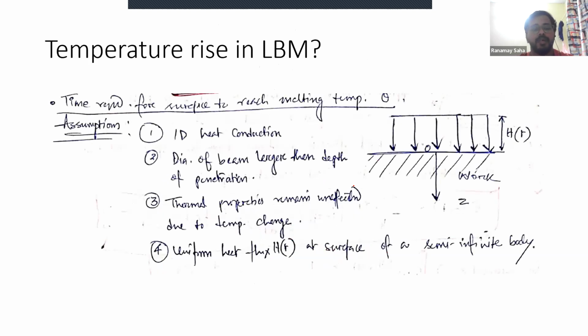Now, we can similarly look at the temperature rise in the case of LBM. However, this needs some assumptions, such as the heat conduction that we also considered in EBM. The diameter of the beam D should be larger than the depth of penetration Z. Then thermal properties remain unaffected with temperature change.